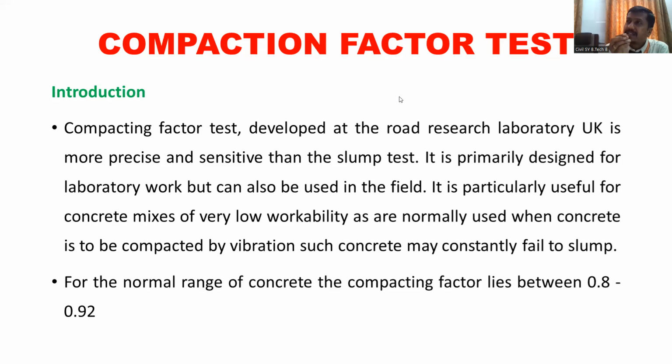Now, if you just take the example of column, at the time of placing the concrete in the column, the concrete is a little bit highly workable. But if you want to use the same concrete in the slab, no, I will not prefer it. I will prefer the concrete which is having the workability in the range of 50 to 75 mm or from 25 to 75 mm. A little bit it is having some low workability.